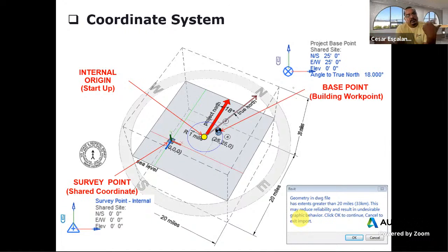But then when we get the information of declination between project north and true north, it is something that we can customize and add to the project base point information. If you notice, the project base point is the point that collects information about the orientation with the true north. Okay, and so when there is a declination angle between these two orientations, you're going to see that the cube box actually rotates and it's no longer aligned with the main geodesical orientations.